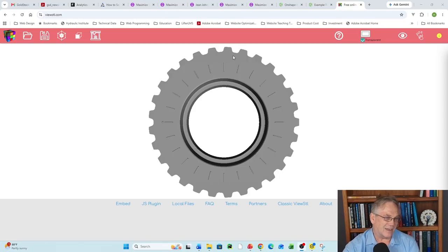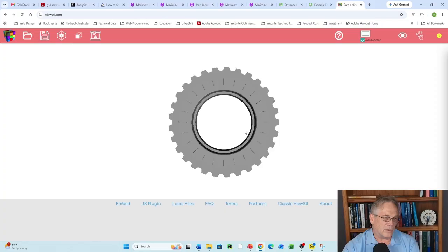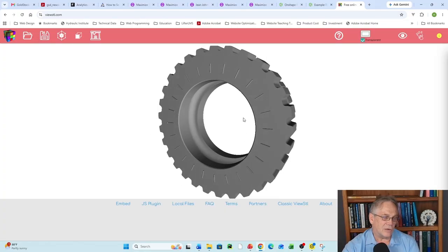So in this particular case, it was important to orient the part horizontally in the machine such that the layer would coincide with this surface over here on the gear, and thus you get the best accuracy on this particular surface and also the best strength on the surface here. And so this is a technique that's used within 3D additive manufacturing.